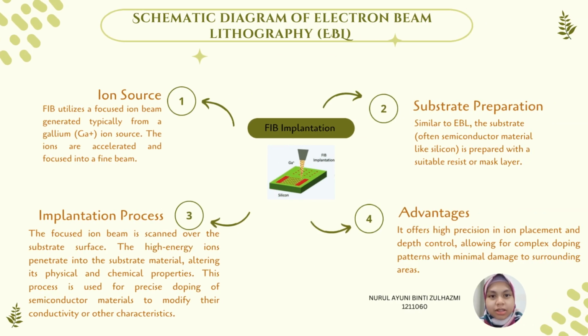FIB implantation. First and foremost, the ion source. FIB utilizes a focused ion beam generated typically from a gallium Ga+ ion source. The ions are accelerated and focused into a fine beam.